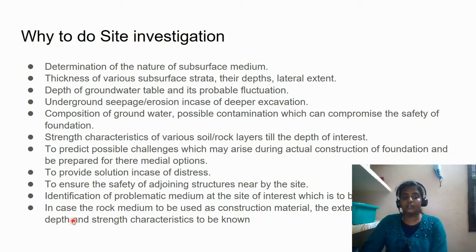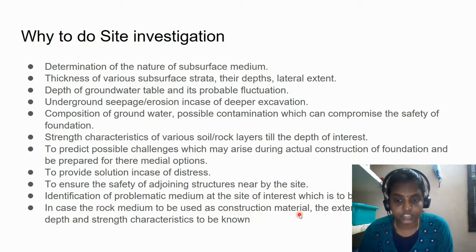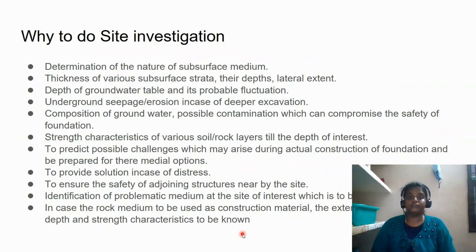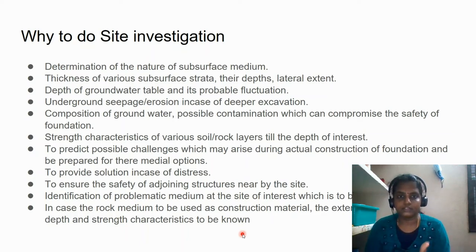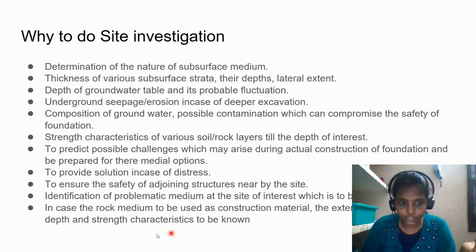In case of rock medium, it can be used as a construction material. Extent of excavation, its depth and strength characteristics are to be known. It is very, very tough to drill in a rock. So when you are going to have a rock medium, you have to assess its strength. What could be the type of the rock? What could be the type of weathering or extent of weathering? That rock might be in the stage of becoming a soil. You know the geological cycle, soil comes from weathering of the rock. So you have to know what could be the extent of weathering in that rock, and what could be the depth we can excavate in that particular site.